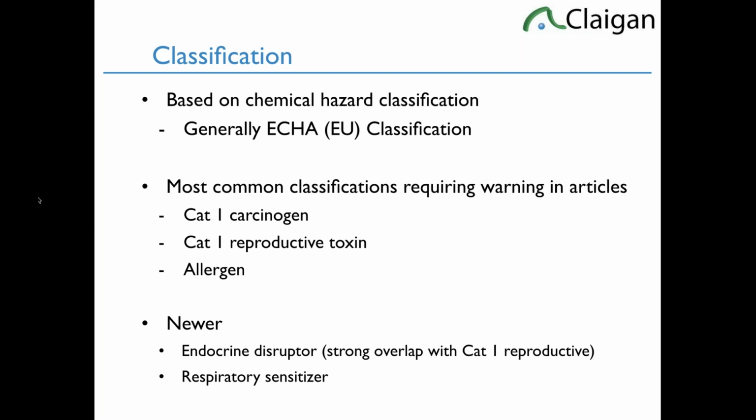Cobalt in the EU in February was reclassified as a Category 1B carcinogen, known to cause cancer in animals, which for most products doesn't mean it's regulated yet. EU MDR means when it kicks in officially next October, it'll be regulated in EU MDR in the absence of anything else happening. The problem is cobalt is up to 0.2% in most high quality stainless steel. It doesn't have to be there, but it generally is, between 0.1 and 0.2. That'll create EU MDR regulatory issues, mostly labeling and justification.